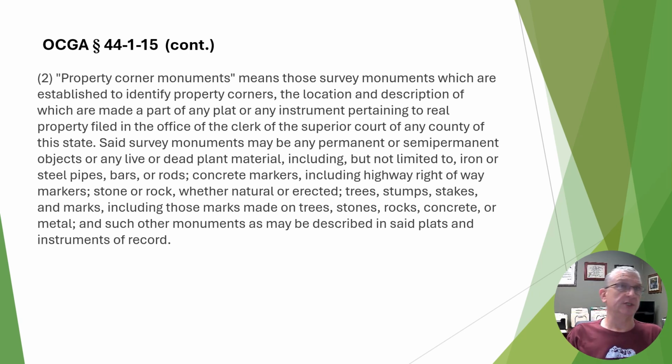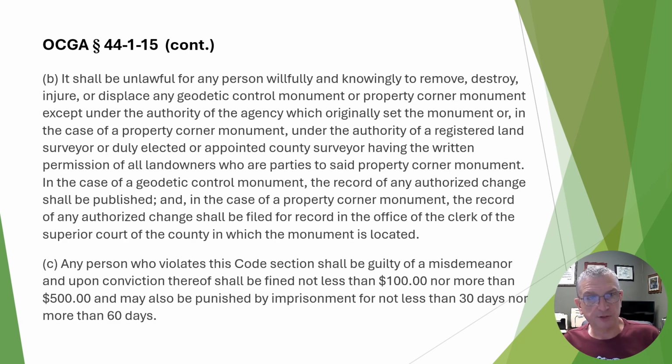Now, nowhere in the state board rules for monuments do we consider marks made on stumps or markings placed on rocks as being elevated to the level of a monument. We look at it more as a precise, fixed, permanent point on the surface of the earth. But even marks made on trees can qualify under this law. So the last part of this section of the presentation is what you would need to know if it comes up, which is paragraph B.